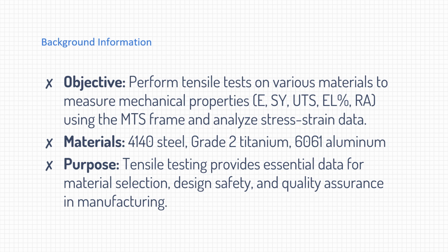The main objective of this lab was to perform tensile tests on various materials to measure mechanical properties, such as the modulus of elasticity, yield stress, ultimate tensile strength, and percent elongation and reduction of area, using the MTS frame, as well as to analyze the stress-strain data collected.